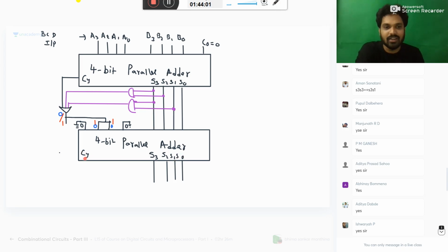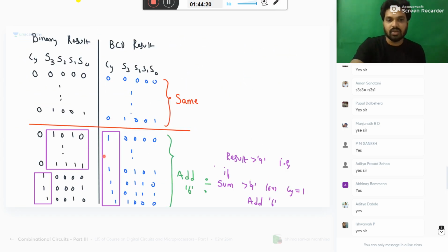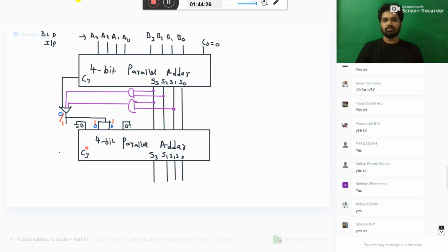I didn't invent anything. I just explained the logic to you. That's all. Now onwards, because of this, you will be able to design anything. That is my intention. So now please tell me, for the BCD result, how to take the carry? I told you now, in the BCD result, when you add 6, it should always be 1. When you don't add 6, it should be 0.